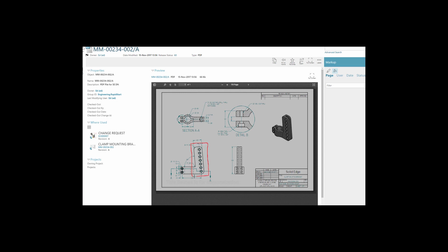And we're just going to box this up in here, and then say, let's move that. All right, so that's my area, but of course I'd have to have a note here to kind of explain it. So we're just going to tell it to move. Well, if I could type here, we're going to just tell it to move that 40 millimeters out. I would probably add additional notes in here, maybe make the change from the assembly or something like that, and just giving notes to whoever is going to make that change.